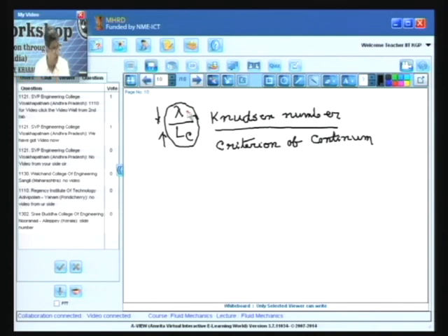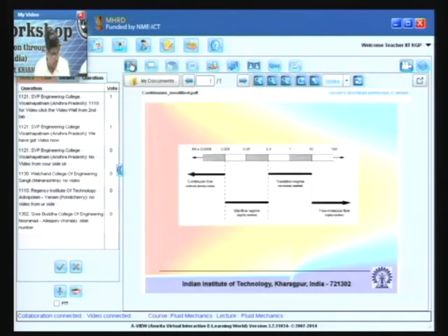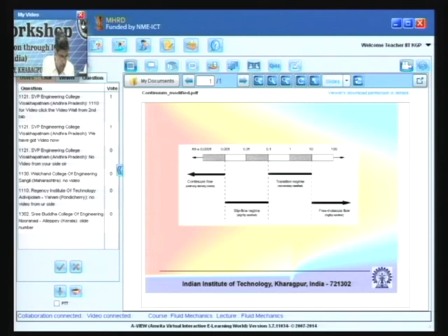So, now I show you with this concept in mind the information regarding these scales that you see in the table: when the Knudsen number is less than 0.001, we consider the flow or the medium to be a continuous medium or continuum with no slip condition.